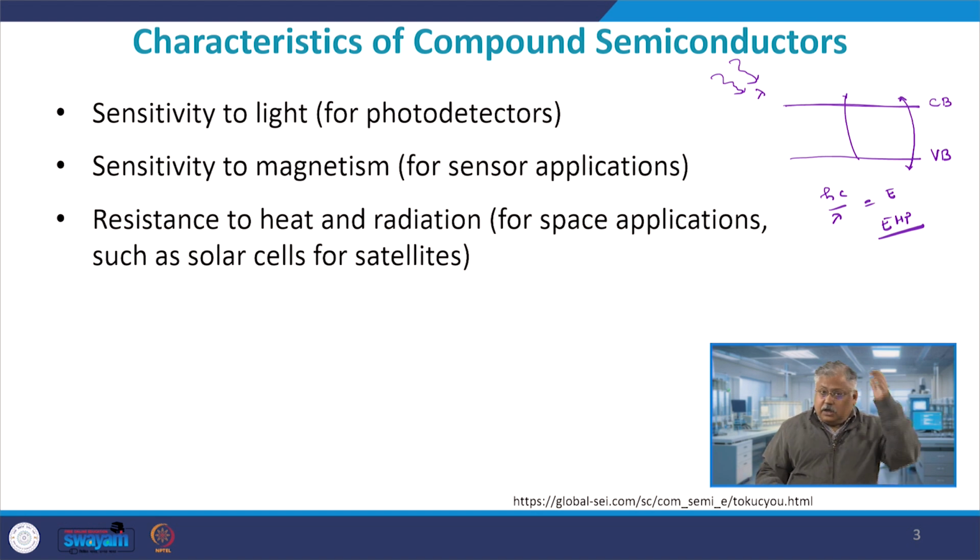However, if the energy carried by the light is smaller than the band gap of the material, then it will just be converted into heat, and the lattice will also increase its heat. If it is more than the band gap, the electron can go much higher into the conduction band. It can release its energy in a thermal fashion and sit at the bottom of the conduction band, such that the total energy loss is approximately equal to the lattice energy loss plus the band gap which is available to us. So, this is how you are actually detecting light in a photodetector, right?